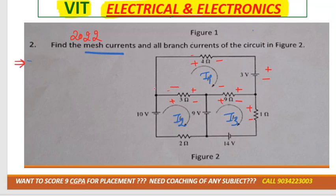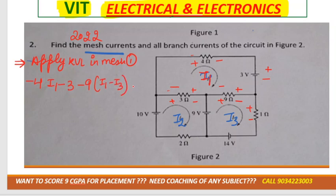Now you tell me the mesh 1 equation. Mesh 1 is the I1 equation, so you have to properly write down, like apply KVL in mesh 1. Tell me. Minus 4 I1, minus 3, minus 9 (I1 minus I3), then minus 3 (I1 minus I2) would be equal to 0.